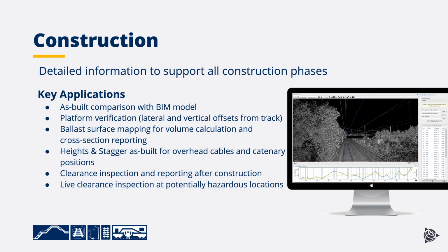The same concerns the heights and staggers. So if we install new overhead lines, we also think about whether the stagger positions correspond to the initial design position. And of course, during the construction phase, it's also always important to monitor the live clearance.